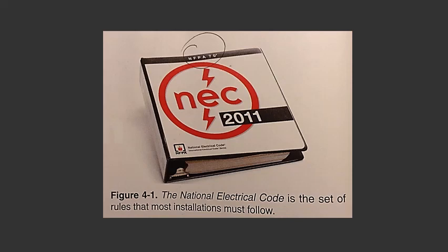State and local codes. Although the NEC itself has no legal basis, it is often made mandatory under local and state rulings. In such cases, it becomes a legal document. The authority having jurisdiction, AHJ, is the person or group of people responsible for approving the equipment, materials, and installation, or a procedure. The NEC is not an AHJ, but the building commission of your municipality may be the AHJ and will probably use the NEC for most electrical installations. The phrase authority having jurisdiction, AHJ, is used instead of a specific title, such as the electrical inspector or county building commission, because the approving systems vary.